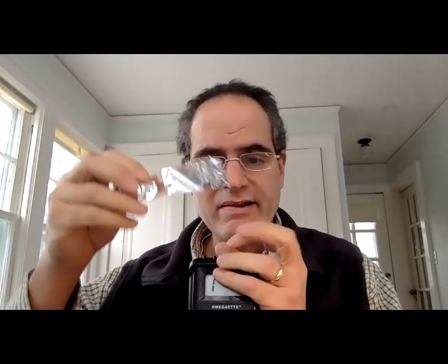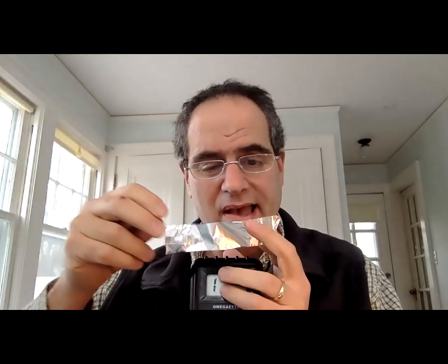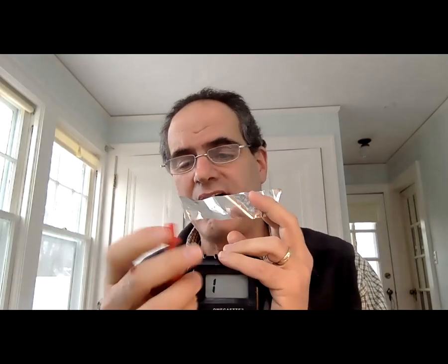What I have here is just a digital voltmeter, much like the ones that you've been sent. Right now it's set to measure electrical resistance, on the 200 ohm scale. Here's a piece of aluminum foil. As you can imagine, aluminum is a very good conductor. It's one of the materials that has the highest conductivity. If I connect the probes to the aluminum, you should see, there we go, that the resistance is very low. It's on the order of a few tenths of an ohm across this strip of metal. Nothing could be simpler, right?